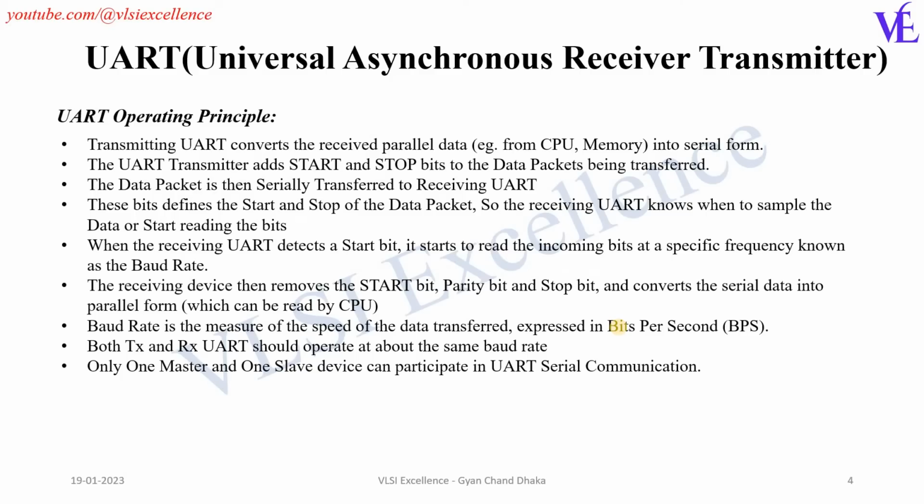Now let's understand the UART operating principle. The transmitter UART converts the received parallel data, for example from the CPU or memory, into serial form. And the UART transmitter adds start and stop bits to the data packet in transfer.